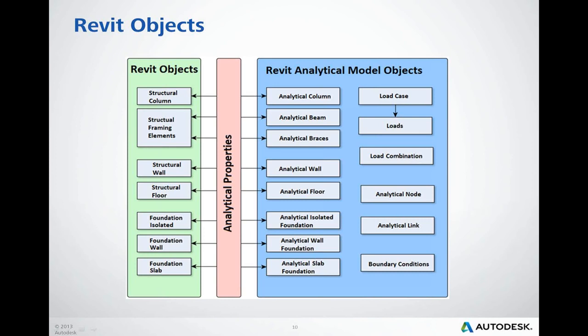Boundary conditions are understood as supports such as point, nodal support, line, area support, which can be applied directly to Revit analytical elements. In Revit, they are available in Analyze tab or during analytical model adjustment, such as analytical nodes and analytical links.